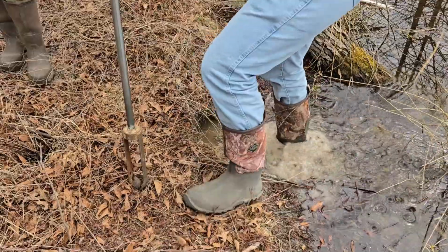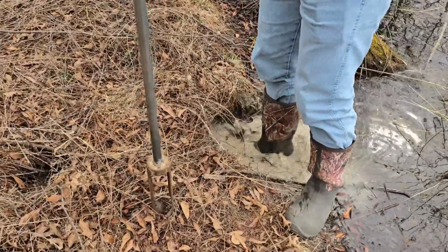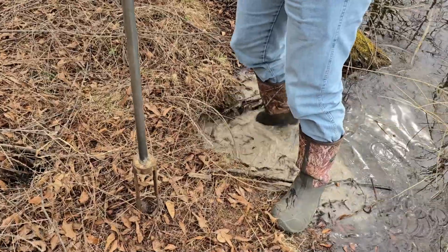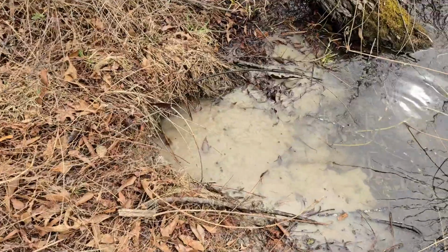You can test to see if a muskrat burrow is draining a wetland by using your feet to muddy the water at the entrance to the burrow. Watch to see if sediment in the water is flowing into the dam.